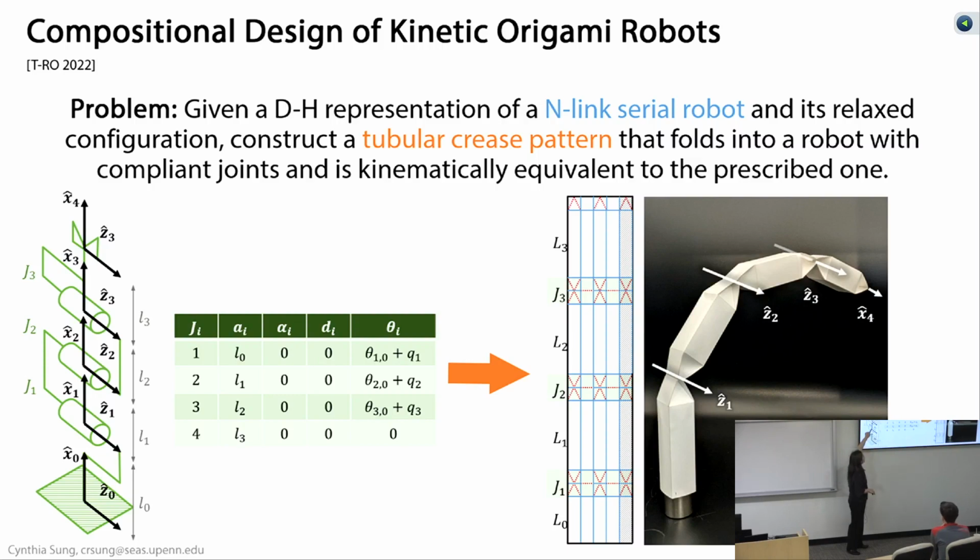So in this case, this is a revolute joint here. We have rotation around this axis, which we called Z1. And so I can describe the location of Z1 relative to the origin using 4 parameters. And then the Denavit-Hartenberg representation is a table of those parameters for every single joint on the arm. So that's high level. If you're interested, there are all sorts of interesting explanations for the details.